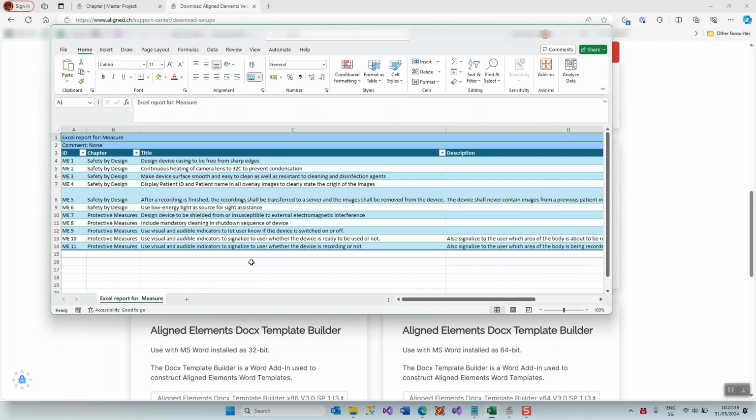Note that the importer works on the convention one row, one design control. The importer will only operate on the first sheet in your Excel document. Now, make sure that you remove any column filters, that you unmerge any merged or spanned cells, and that you remove any empty rows or rows that are not to be imported.